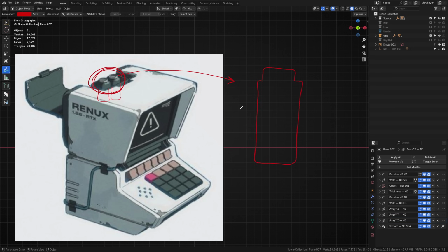If we remember back to the deconstruction section, I showed you an example of a revolution extrusion. That seems to be the most applicable here. We have to identify a seam, which is easy enough with a shape. We can draw one going right down the center. Then, if I carefully erase one side, we're left with a usable profile or sketch. If you were to revolve the sketch around the z-axis, we'd be left with a shape resembling the battery.